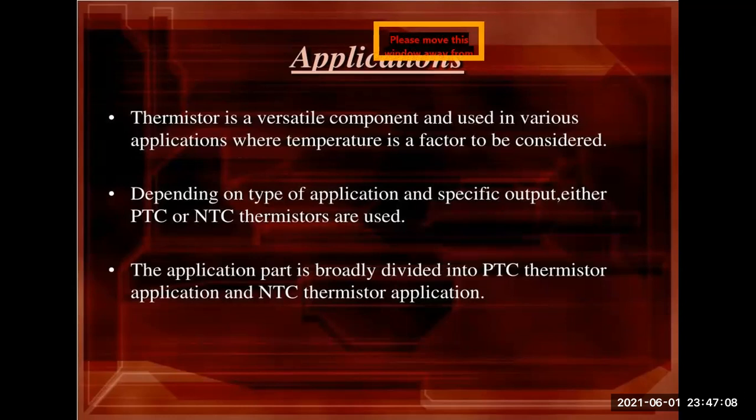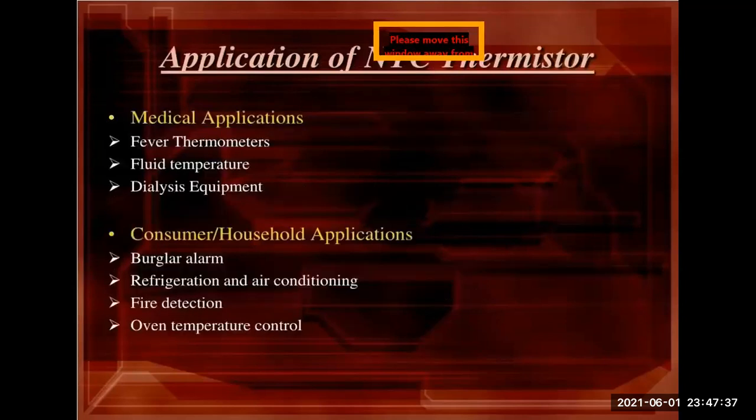When we talk about thermistor, then definitely the relationship between the resistance and the temperature will come into existence. Depending upon the type of application, we'll use either positive temperature coefficient or negative temperature coefficient. The application part is classified into positive temperature coefficient thermistor and negative temperature coefficient thermistor.